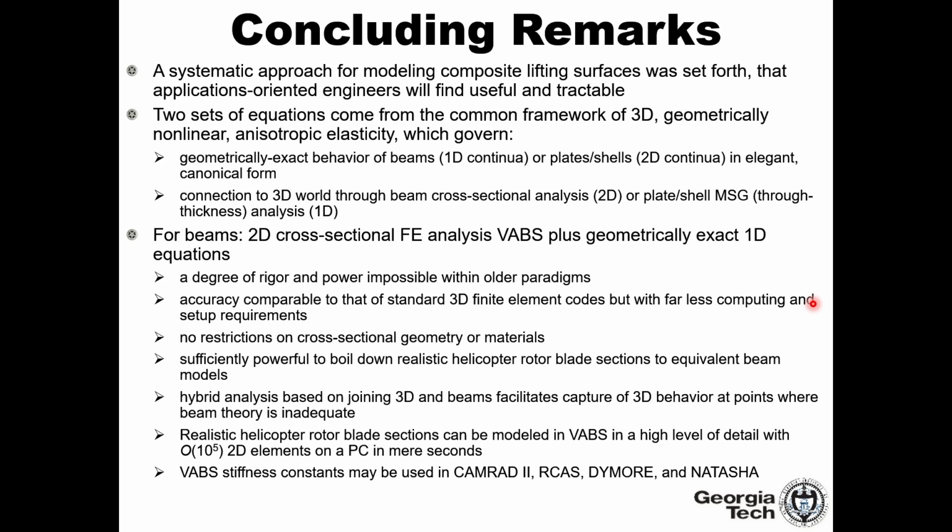So in conclusion, I have presented a systematic approach for modeling composite lifting surfaces and in two sets of equations that come from the common framework of 3D for beams as well as for plates. For beams, we have a degree of rigor and power that would be impossible with the older paradigms that I faced when I was right out of graduate school nearly 50 years ago. There's no restrictions on the cross-sectional geometry or the materials.